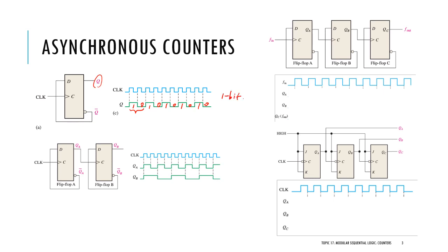asynchronous counter. And if we add a second D flip-flop, but we use the output QA as the clock input for the second flip-flop, we can figure out the outputs for QA and QB look like that. Now if we write the output down, we got 1 1 in this cycle, and then 0 1 here, 1 0, 0 0.